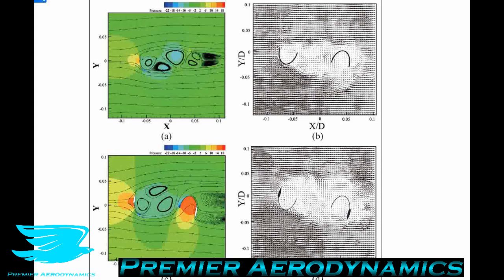Accompanying this different wake size is the fact that there seem to be several vortices, and interestingly, these vortices also appear for the lift and drag blades. So you can see here we get 3 vortices effectively, and then downstream we have 2 vortices here. The only difference is in this downstream blade, we get 2 vortices for the drag only blade, but none for the lift and drag blades.